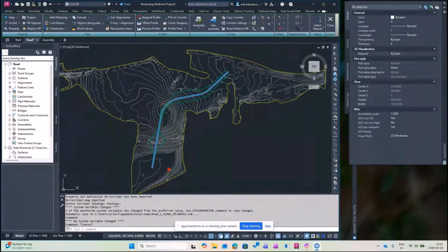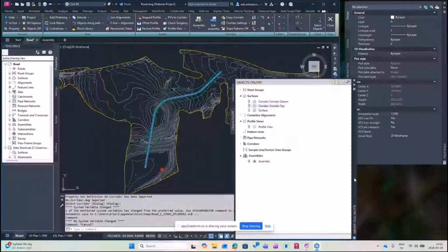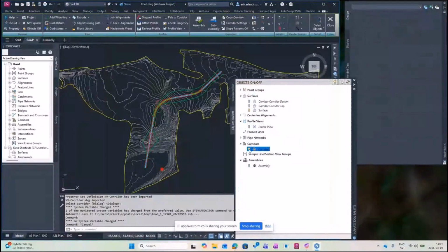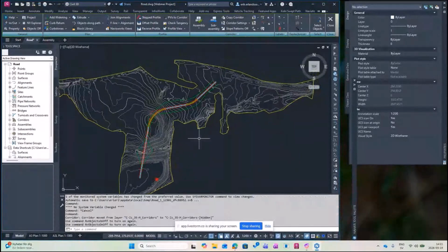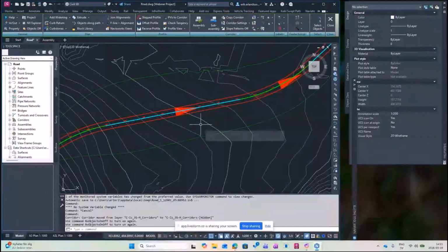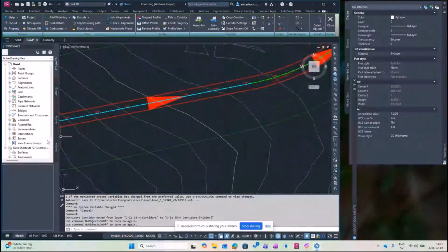Let's hide our corridor to see our line objects. So I go into Objects on off, and I hide my corridor. We can now see our line objects, and it's time to add some slope patterns. Slope patterns creates clean, perpendicular, uniform slope lines between selected geometry. Whether from corridors or polylines, these lines are 3D polylines, so you can copy them directly into your export file.